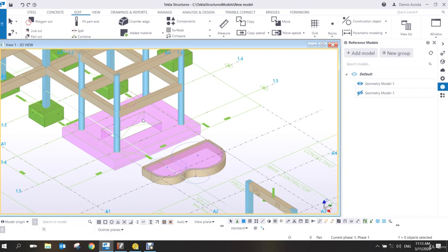IFC is also a 3D, right? Let's say you have the IFC MEP, and then passing through the beam in Tekla Structures. Even though that one is IFC, let's say from Revit, you can do the clash checking between the IFC and Tekla Structures element. It will highlight to you if that one is clashing, as well as the drawing, even though it's a third party. Okay, so kindly try that one.